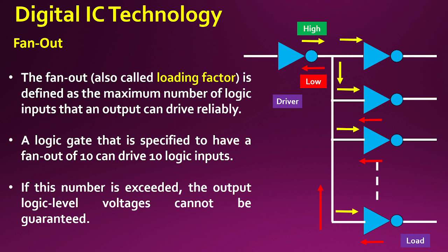From our previous discussions, we have already understood that when a particular driver TTL is at high logic, a current will source out of the system. It has been shown by the yellow arrow marks. So we can see a current is getting out of the system if there are these many loads connected. Then, depending on the consumption of each and every load TTL IC, the current will get added up.